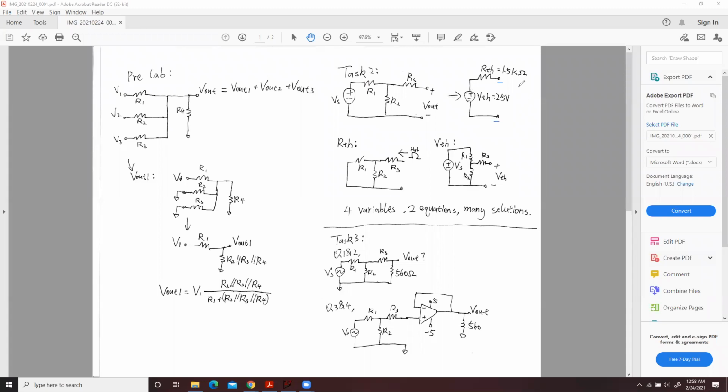The only thing you can do is deal with these two nodes. For example, you can use a DMM to measure the resistance, or you can use a voltmeter to measure the voltage. You can use an ammeter to measure the current. Whatever method you use, you can only deal with these two points, and then you use those methods to get the values RTH and VTH.